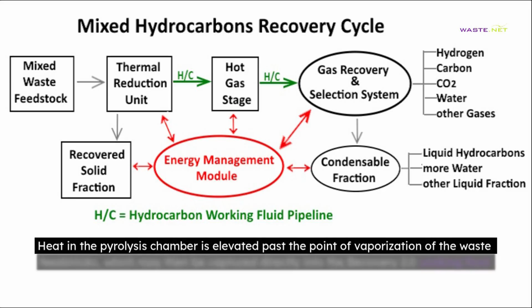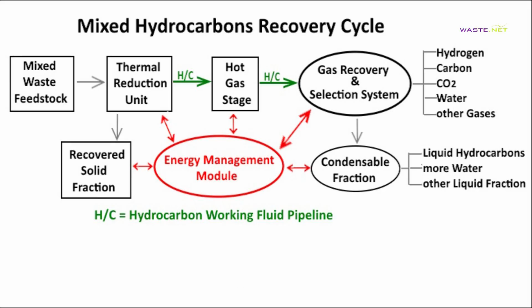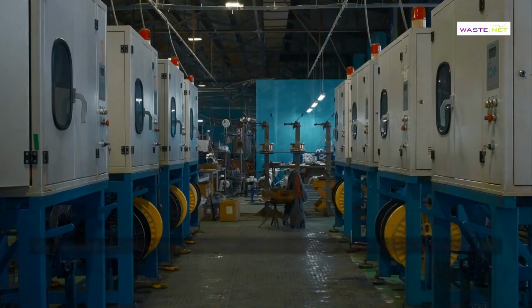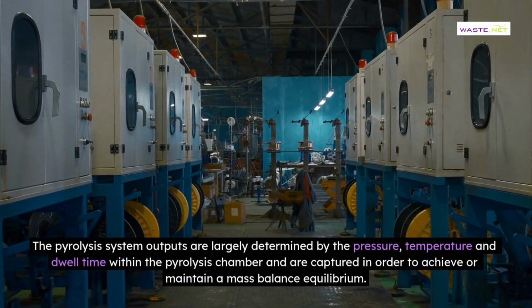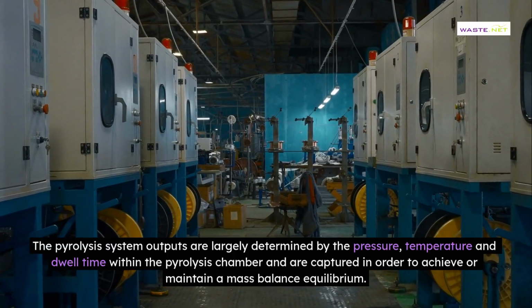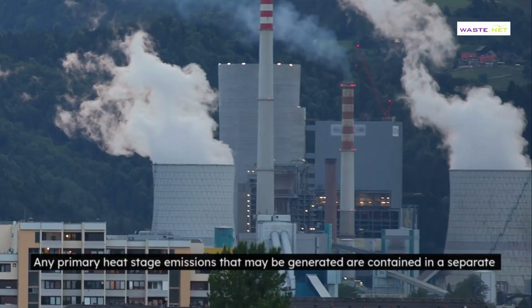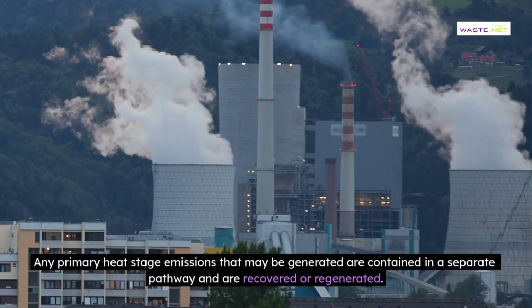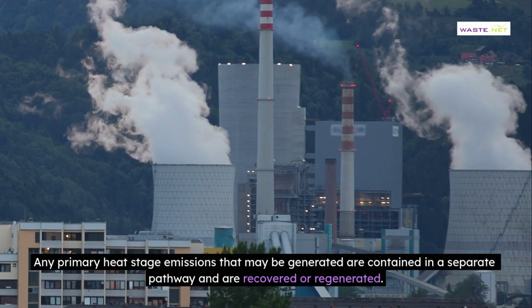Heat in the pyrolysis chamber is elevated past the point of vaporization of the waste feedstocks, which may then be captured directly into the Recovery 2.0 working fluid pipelines. The pyrolysis system outputs are largely determined by the pressure, temperature and dwell time within the pyrolysis chamber and are captured in order to achieve or maintain a mass balance equilibrium. Any primary heat stage emissions that may be generated are contained in a separate pathway and are recovered or regenerated.